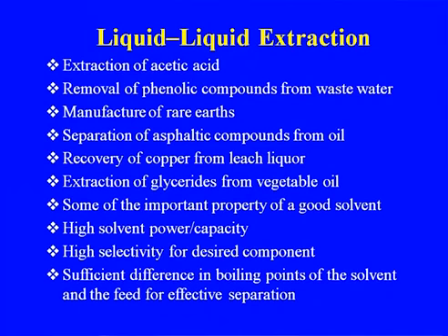Some of the important properties of a good solvent, because the choice of solvent is also very important: high solvent power capacity, high selectivity for the desired component, and sufficient difference in the boiling points of the solvent and the feed, because you will have to strip the solvent from the product, and separation is only possible when there is sufficient difference in boiling point.